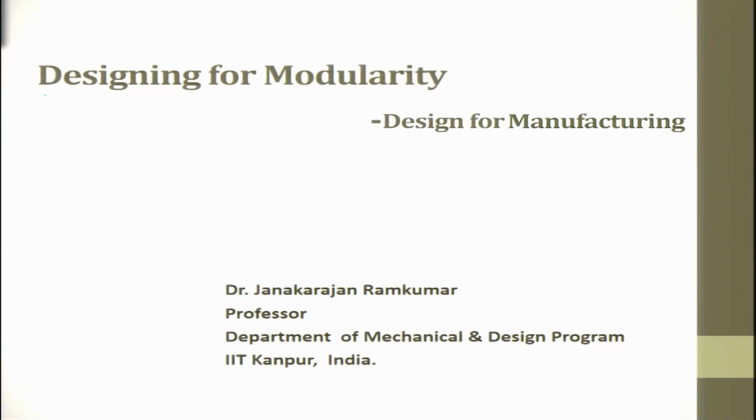Welcome to the next lecture for our discussion in this course on rapid manufacturing. We are now going to focus on design for modularity. As it very clearly says, modularity. That means design has to be thought of in modular form, or I have to make the parts or the design in modules. So, what is that? It is something like a library function we have predefined, and these library functions are ready. Whenever you want, looking into the requirement, you pull up the material from the library function, modify it a little bit and then start using it for the final product.